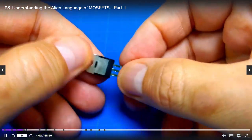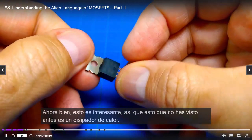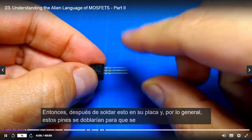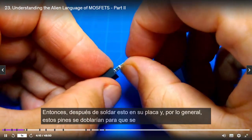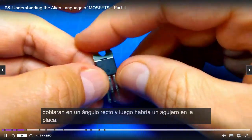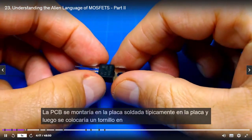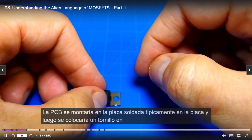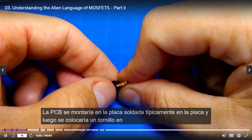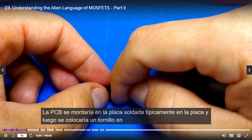All right, and now, so this is interesting. This thing, you haven't seen this before. This is a heat sink. And so after you solder this into your board, typically these pins would be bent at a right angle. And then there would be a hole in the board, the PCB. This would be mounted onto the board, typically soldered onto the board. And then a screw would go down into it.